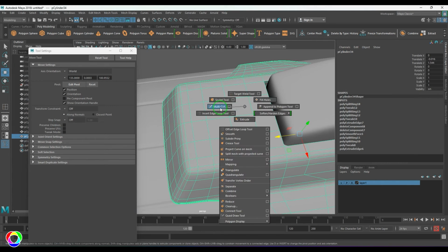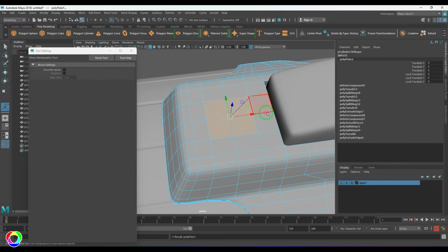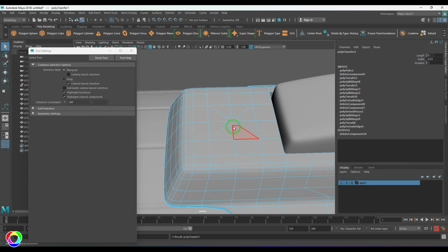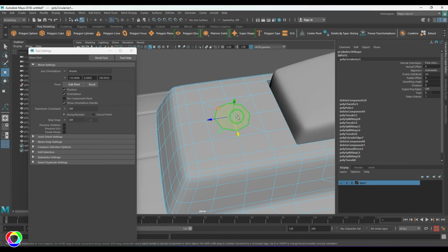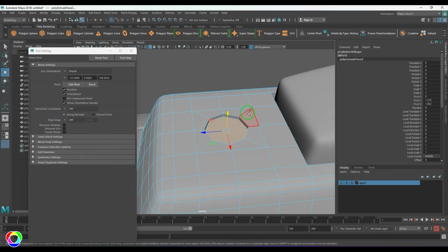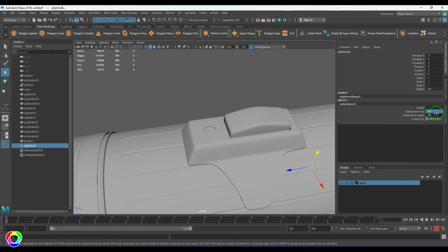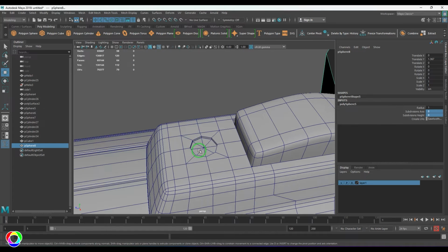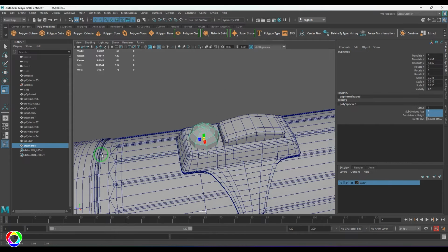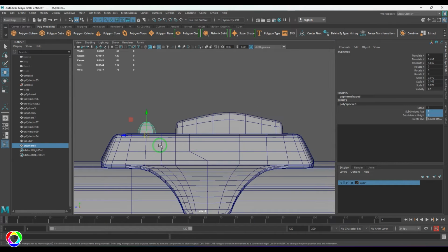Okay, so I'll use the multi-cut tool, or maybe I can select this edge, delete those edges, apply poke face, and then select that vertex, chamfer, and then select that and then circularize like that, and then extrude it down, extrude it and merge it to the center, and then bring up the 8 subdivisions and then snap it here at this point, and I'm going to scale that like that up.